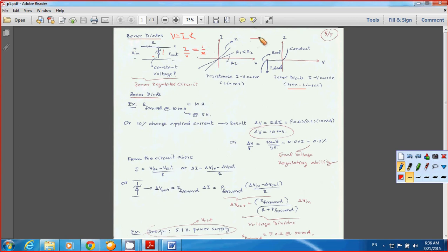And you need to supply positive on this one and negative to this one to be able to conduct the current, and that's what we call the forward bias. Okay, so don't worry about that. I will discuss the diode characteristic later on. But in this case, we are interested in how the Zener diode connects to the circuit and how it keeps the output voltage constant. There's a lot more to talk about diodes.